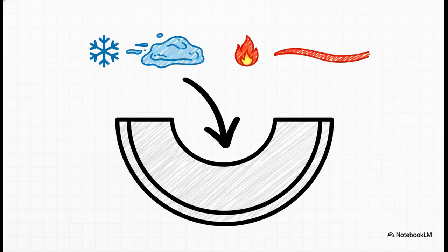Fluid viscosity, how thick or slick the fluid is, varies heavily with temperature. Just think of cold honey versus warm honey. Huge difference, right? Because the fluid right up against the wall is at a very different temperature than the fluid flowing in the middle, the viscosity right at the wall is totally different. So when your equation calls for surface viscosity, which is usually denoted with a little s subscript, it absolutely unconditionally must be evaluated at the surface temperature. If you use the bulk temperature for this, your whole calculation is going to be way off.